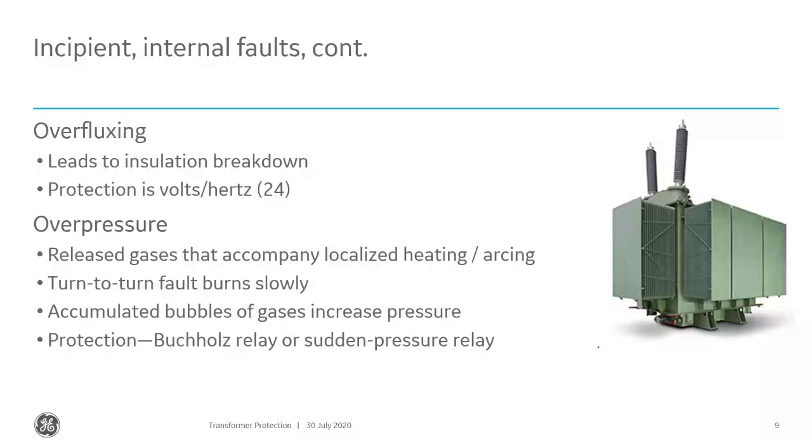It really depends on the physical design of the transformer as to which one of those you use. If the transformer has a conservator tank, a big tank sitting up here with pipes down in there, then it's going to have a Buchholz relay. If it doesn't have that conservator tank, it's probably got a nitrogen cabinet sitting here with a bottle of nitrogen. That nitrogen tank keeps a nitrogen blanket on the top of the transformer up here. Those sort of transformers would have a sudden pressure relay sitting on the top of the transformer.